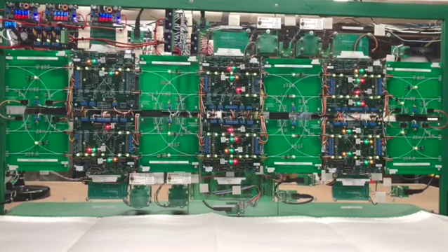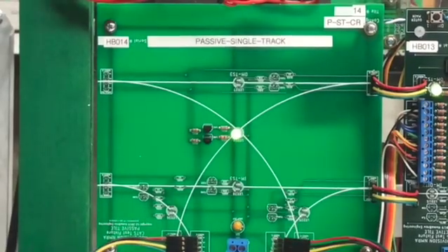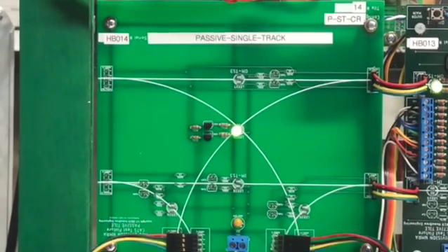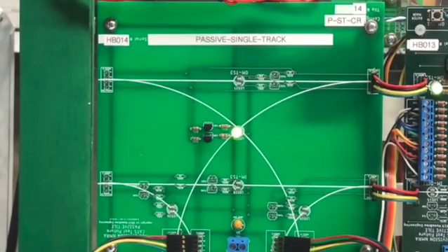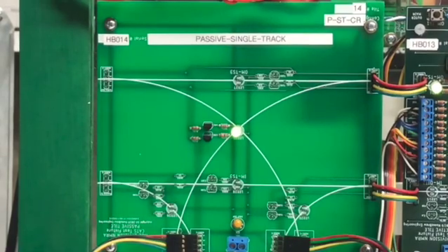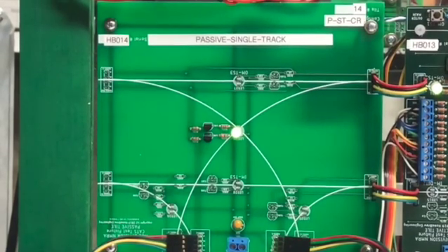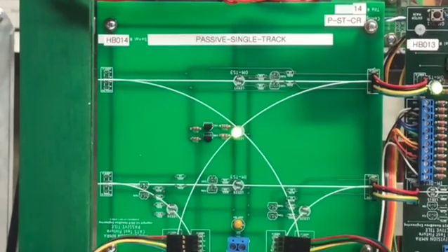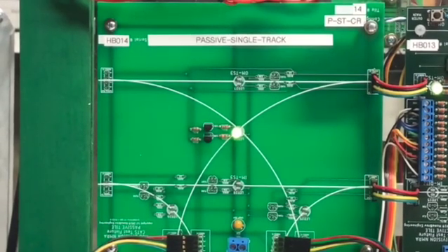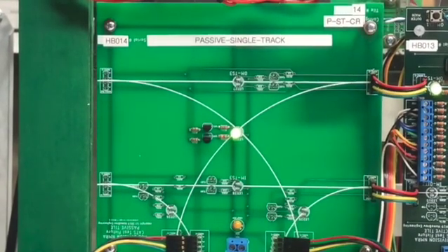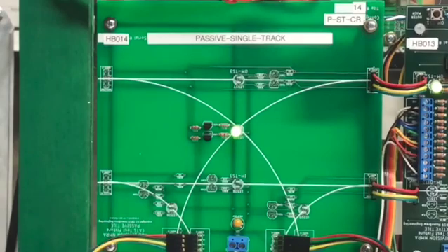Let's zoom in to each module, starting with the passive corner in the upper left. The only track indicated here is the arc from the lower left to upper right, and the LED is green, indicating that the block is not occupied. This LED receives its occupancy indication from one of the adjacent modules over those jumpers I just described. Remember, there's no active signaling circuits on a passive module. When we get to the CATS panel associated with this test bed, you won't see a distinction between the curved or straight modules. This is a physical characteristic that gets linearized when the panel is made.